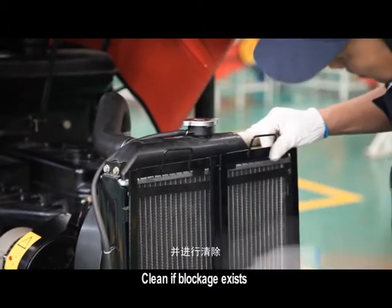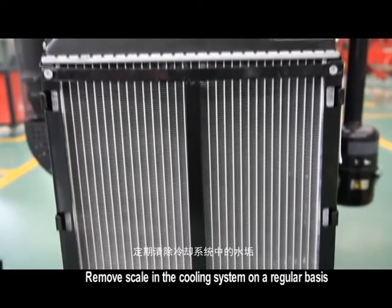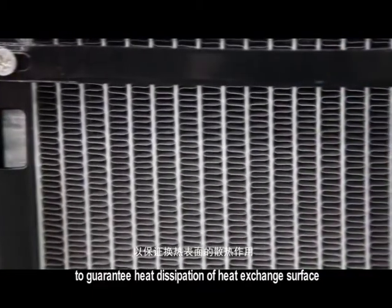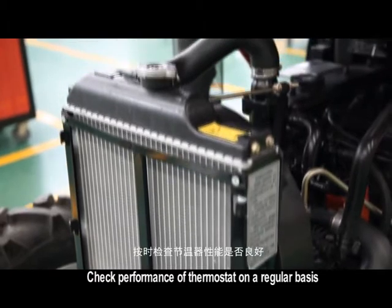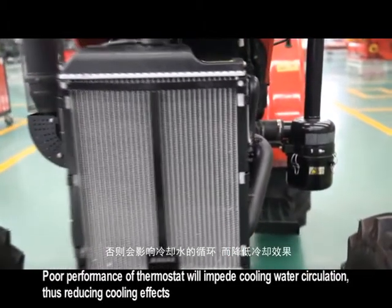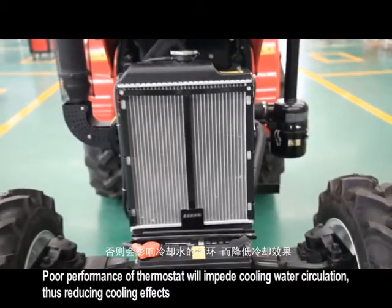Clean if blockage exists. Remove scale in the cooling system on a regular basis to guarantee heat dissipation of the heat exchange surface. Check performance of the thermostat on a regular basis. Poor performance of the thermostat will impede cooling water circulation, thus reducing cooling effects.